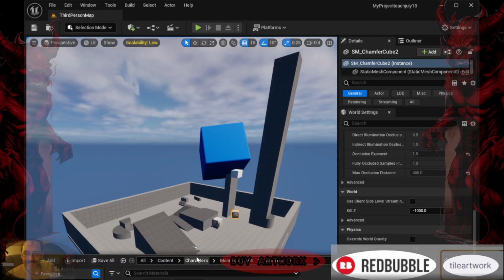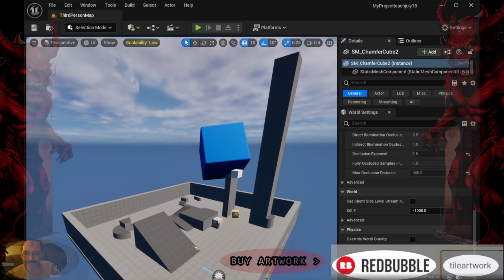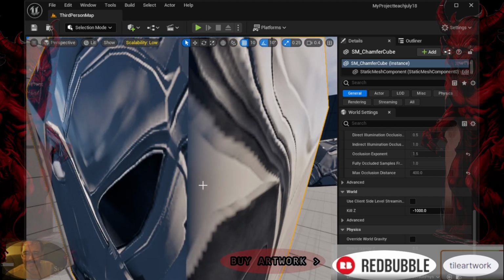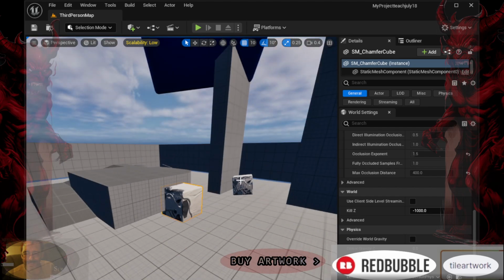Details panel. In some cases, when you have an object selected in the viewport, you might want to locate it quickly in the World Outliner or Content Browser. Right-clicking on the object in the Details panel and selecting Select in Viewport will center the viewport on that object, making it easier to manage and edit its properties. 3. Workflow efficiency. Select in Viewport enhances workflow efficiency by reducing the time spent navigating through complex scenes or extensive lists of assets. It allows you to focus directly on specific objects of interest, whether for editing, positioning, or further